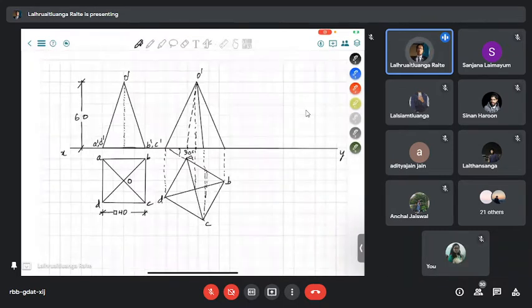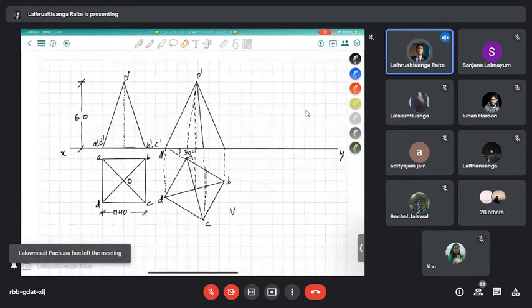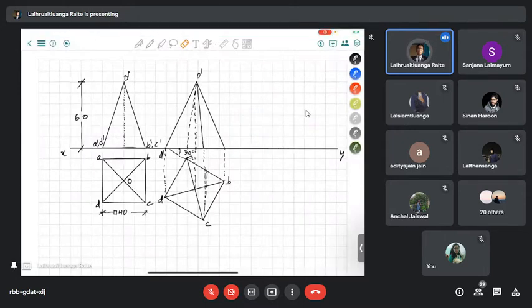Demarcation will go D dash. Sometimes it's better to pull your drawings a little bit downward. For me, I really wanted to fit it in one screen so that you can see it. You can pull it down so that you have more room for annotations. That's always helpful. If you have no restraints, like the center or the axis being a certain dimension from the XY line, then you would have to abide by that. But if you do not have such, then you can simply pull all of these things downward and make your drawing more legible.